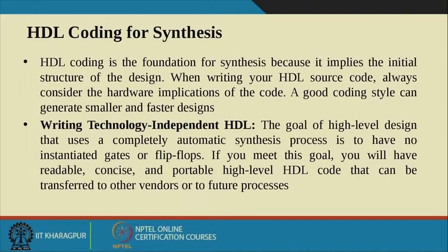Then, HDL coding for synthesis. A good coding practice can give better results in terms of compilation time or other optimization during the synthesis process. HDL coding is the foundation for synthesis because it defines the initial structure of the design. When writing your HDL source code, always consider the hardware implication of the code. A good coding style can generate smaller and faster designs.